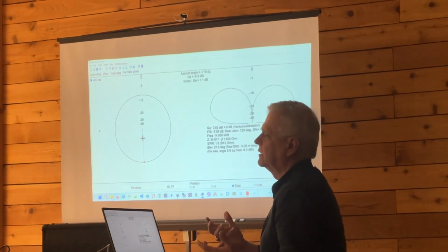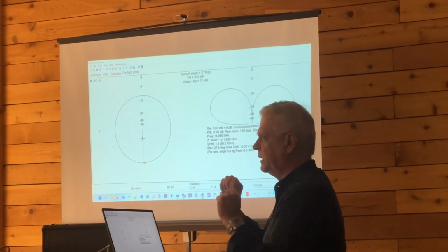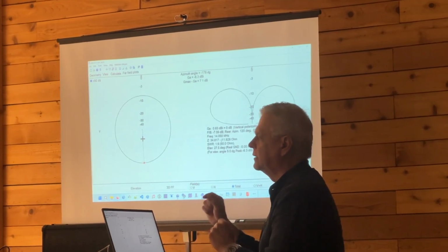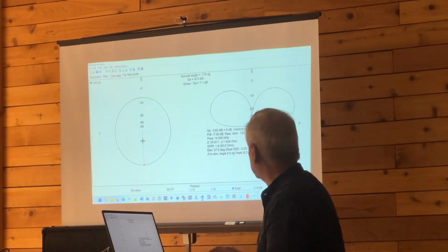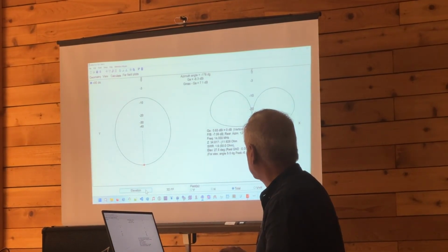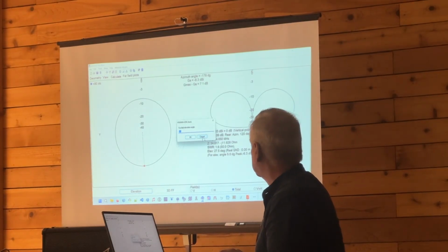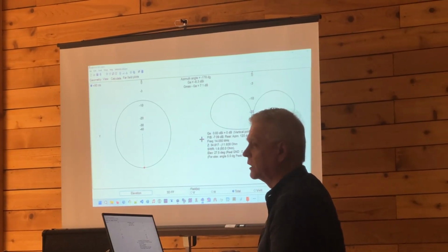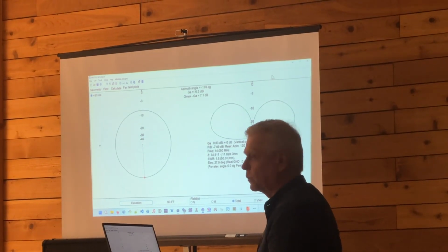And you can watch Callum's videos of the DX Commanders, and he'll make a very important point, which is when one buys an antenna, one can get, well, the gain is going to be 7 dB. Okay, great. But they may neglect to tell you at what elevation angle. And we've just seen that at this elevation angle it is 6.3 dBi. We change the elevation angle to something else and it will be different. So this is important for what we want to do, which is DX. Okay, so that was that.